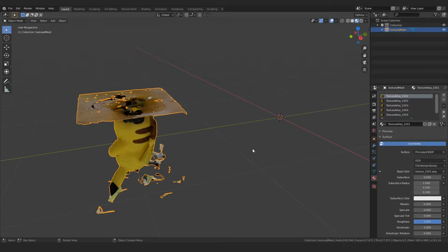Later on, I'm going to show you how to pack your image textures into the Blender file, so that way when you move your Blender file, your textures go with the file. Now, if you for some reason save this Blender file and you move it away from where those images are, because what Blender's doing is it's taking a reference to where that file is located on your computer. In specific, wherever I imported that from is where Blender's going to look for that.